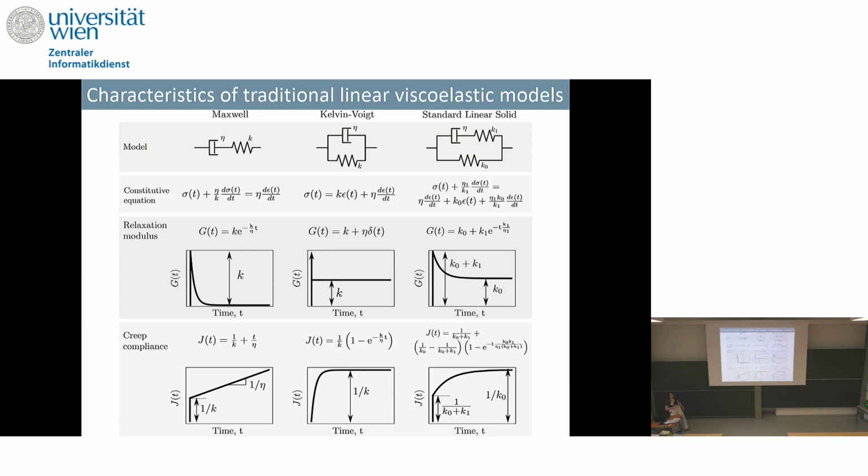What you can do now, I haven't done it, but you can do for fun, or if you want to test, is derive the differential equation for the standard linear solid model, which is another very commonly used configuration. You can use the tools that we've developed for the Maxwell and the Voigt, because we have 2 elements in series, so we apply the conditions we did for the Maxwell, but then we have 2 branches in parallel, and we apply the conditions that we did for the Kelvin-Voigt. Again, you solve for the step in strain.